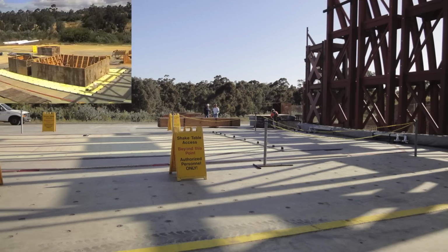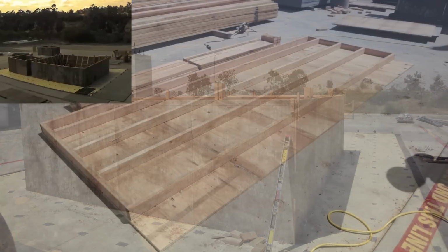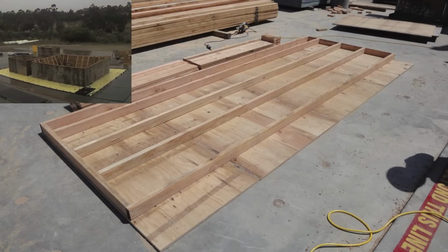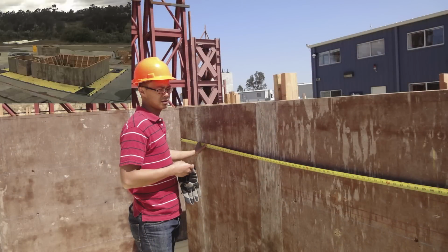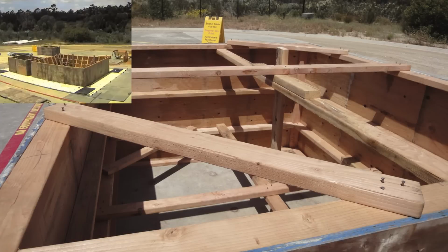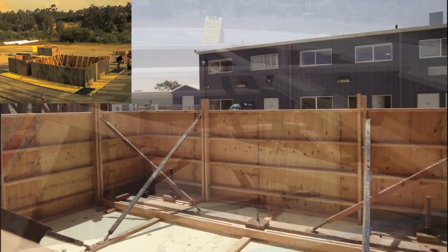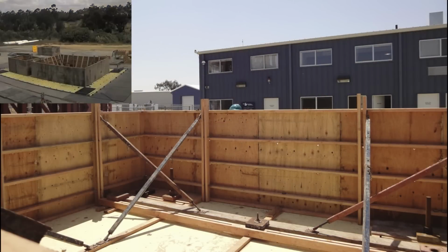Depending on the design of the foundation, the formwork may often require both an interior and exterior segment to support the structural foundation components. In the 5-storey building test, the interior formwork is installed first. To install formwork, wood panels are cut to the appropriate dimensions and are fastened tightly with horizontal beams in order to avoid leakage or failure of the formwork. After the installation of the interior formwork panels, braces are built to resist the actual weight of concrete and the outward lateral force that develops during the curing of the concrete due to thermal expansion.